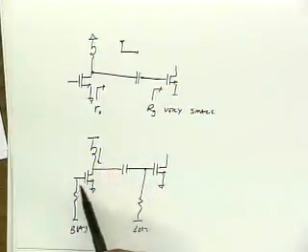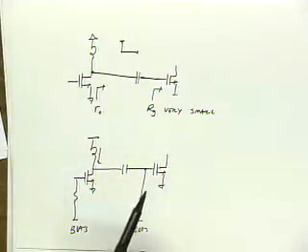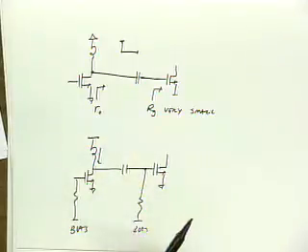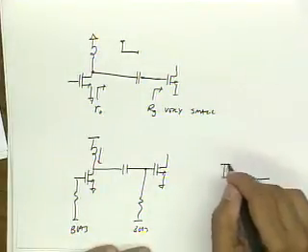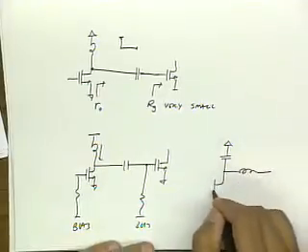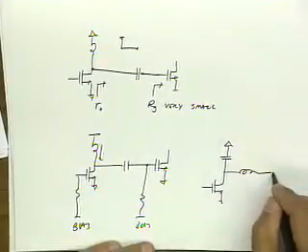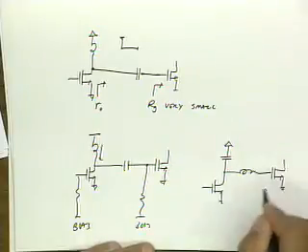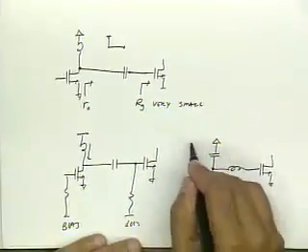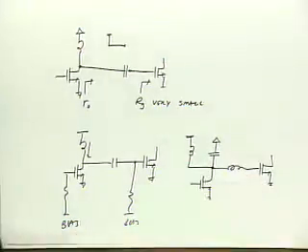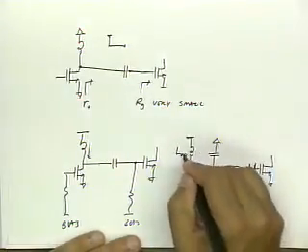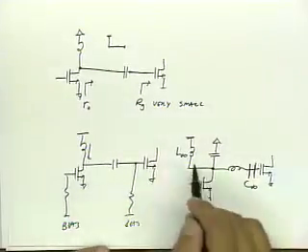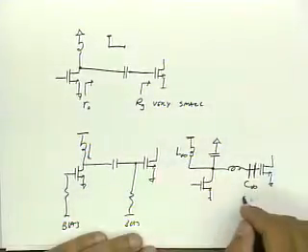It's high-pass filtering. In that case, we would use the other termination, but we'd end up having to put in a lot of extra elements. So, for instance, if I wanted to do a low-pass, do something like this, but I still need to provide DC current, so I actually need another inductor here. And now, basically, I need to provide another capacitor. So this is L infinity and this is C infinity. We call this a choke and we call this a coupling capacitor.